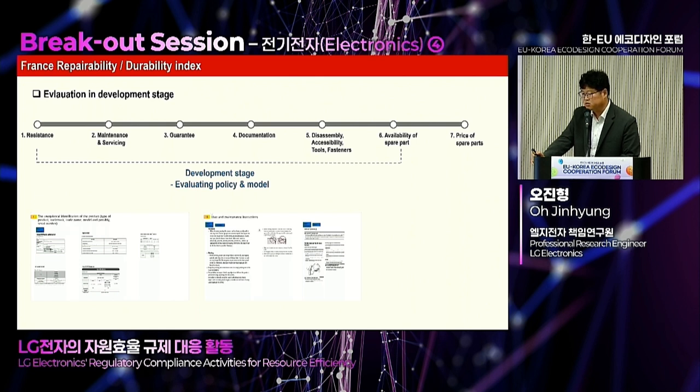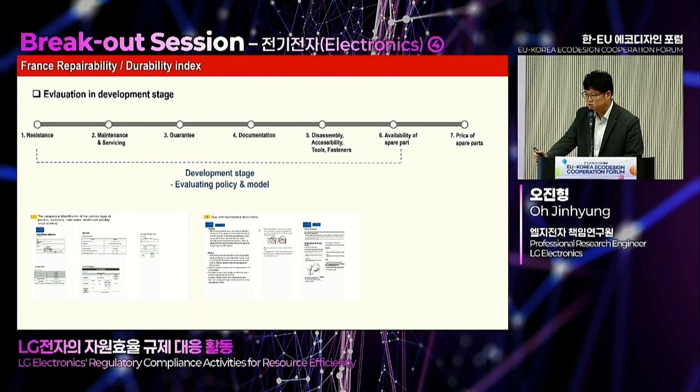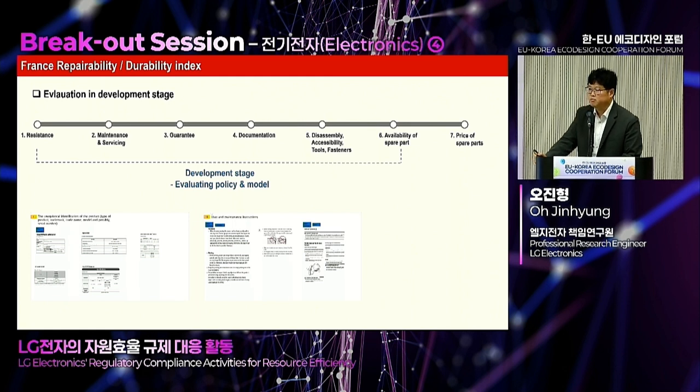So that is directly associated with the life of a part and the relevant testing. So we conduct testing by module to identify resistance, and the same is true for disassembly. So we have designated service parts that need to be disassembled by product category. How many steps are required for disassembly of a part? And what kind of fastening components are required during disassembly? That's why we are testing these during the development process.